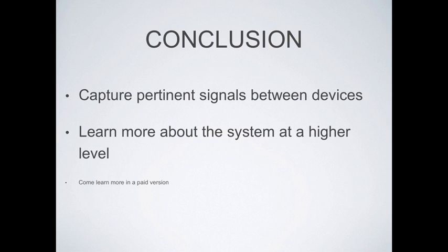And in conclusion, there's a lot of stuff that you can do, a lot of bus analysis and signal analysis between devices, so long as you know what you're tapping into. Any of the serial communication protocols that we're talking about, you can see those and you can sniff them. You just have to be clocking at the right level, the right sampling rate and whatnot.